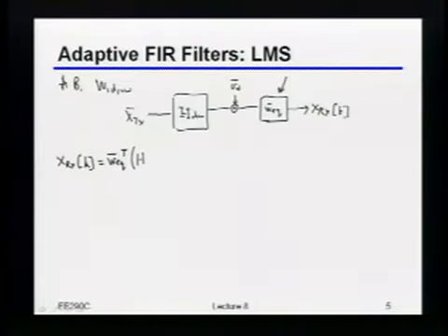I'm going to convolve that with whatever the channel did to my transmitted sequence, and that's of course going to add in some noise. Just to make things clear, I'm going to call this thing over here U_RX. In other words, it's the analog voltage going into the equalizer. So this whole thing is now just going to be that W of the equalizer times U_RX.